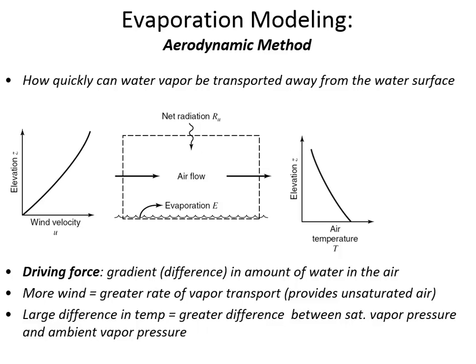Where we'd say that at the center of the pipe the velocity is high, but at the edges of the pipe the water velocity is very low. In fact, right at the border between the pipe and the water, the water is stuck. It has no velocity. There's a boundary layer of water that's stagnant and not moving because the shear forces of the pipe are pressing on the water and holding it stationary.